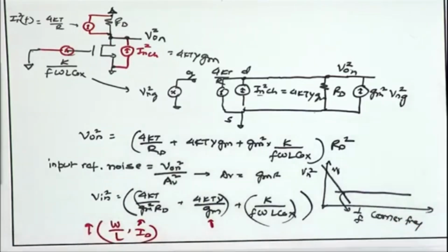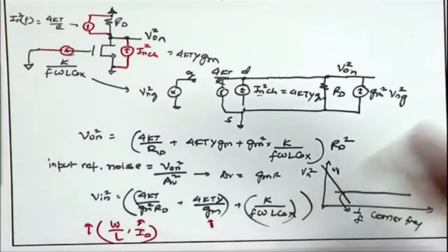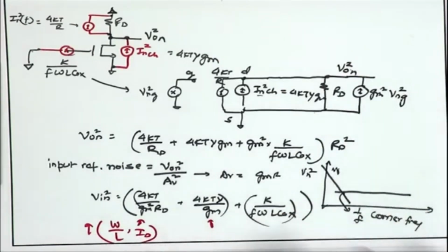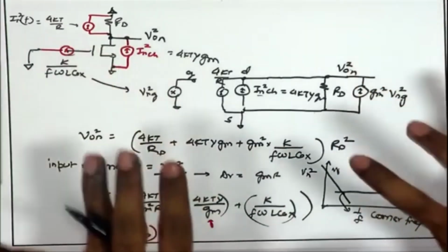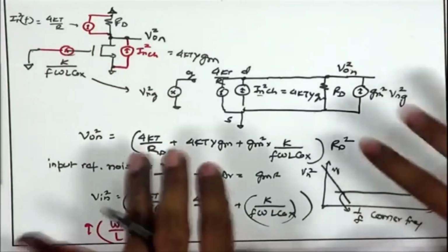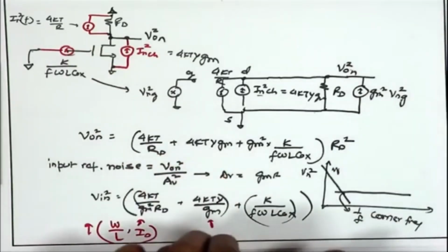This is the scheme overall, starting from DC analysis, DC biasing point, going to small signal low frequency analysis, frequency response, transfer characteristics, the magnitude and phase response, and finally the noise analysis. So, these are the 4 basic tools we are going to repeatedly use in designing more complicated building blocks for our analog front end.